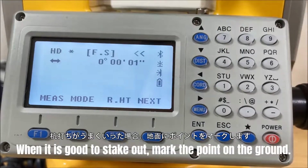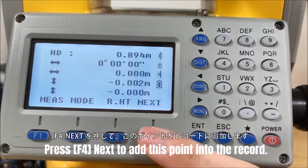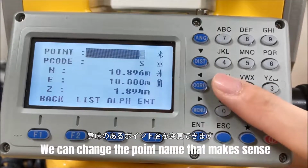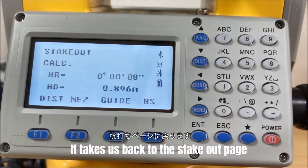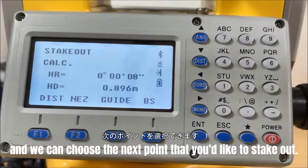When it is good to stake out, mark the point on the ground. Press F4 next to add this point into the record. We can change the point name to something that makes sense. And then, it is recorded. It takes us back to the stake out page and we can choose the next point that we'd like to stake out.